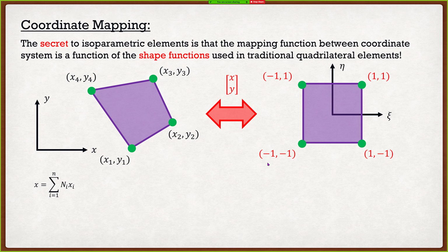So in this case, with 4 shape functions, we can expand the summation for our particular element into this, where we have n1 times x1, n2 times x2, n3 times x3, plus n4 times x4. Nice and easy. The reason why you said 8, I know exactly why: I'm only accounting for the x direction. What about the y direction? It's the same thing: our shape functions multiplied by our y coordinates. So it's n1 times y1, n2 times y2, n3 times y3, n4 times y4.